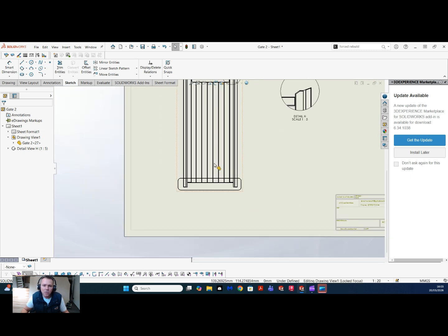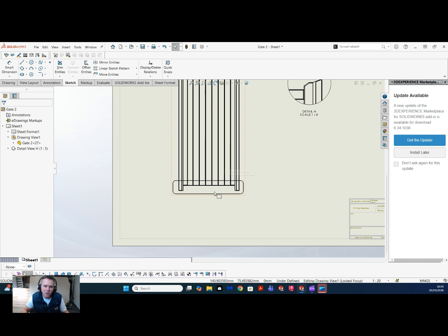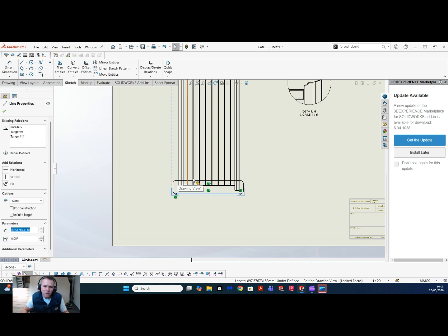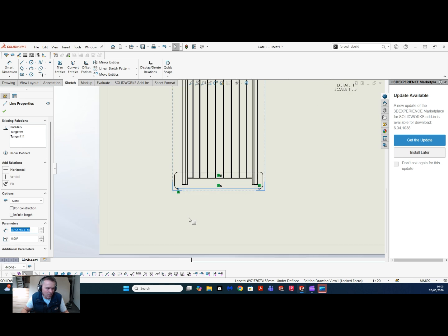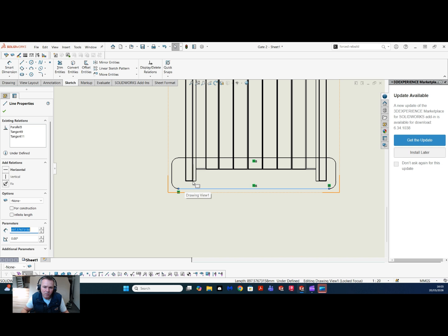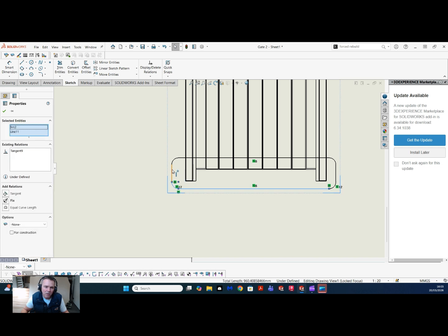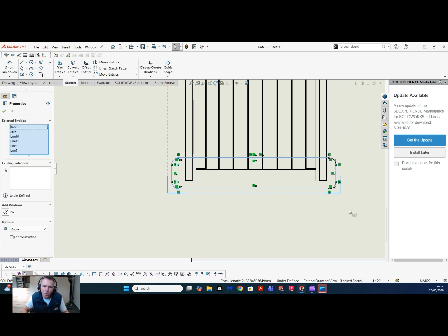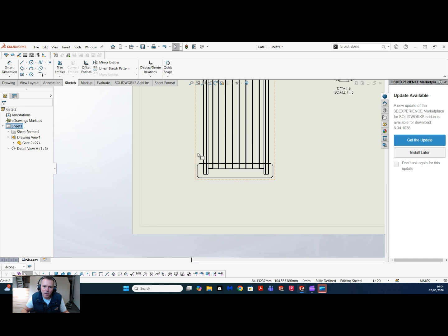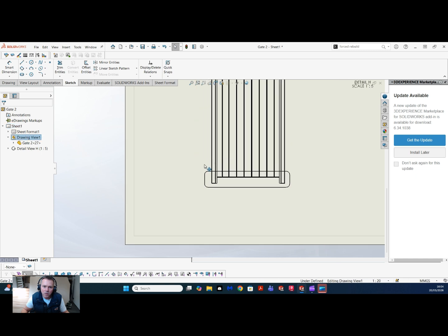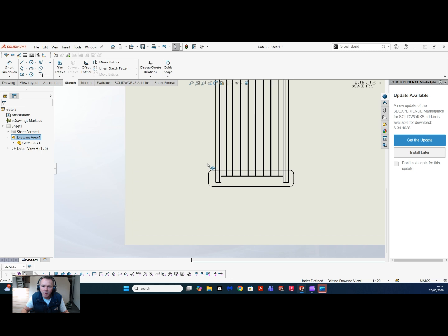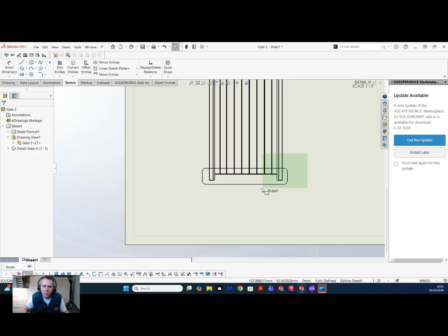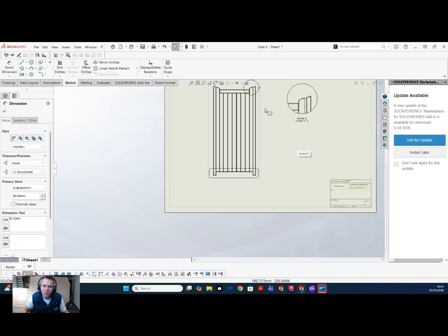And then what we need to do to create the detail is to highlight all of these elements, which you can do by pressing the Shift key down to select multiple items. So you can click them one by one like that, or you can use the Group Select tool. Well, it's moving that around a bit at the moment, but you can drag and group select. Now this probably won't work because I'm off the viewport. So you can see the dotted line out here.